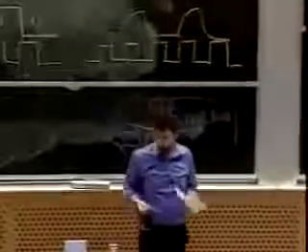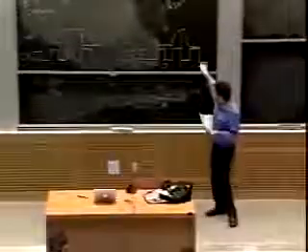If we're not careful, we're going to get something that's wrong. In this case, I transmitted 1010, but now I'm decoding something that's shifted from that somewhat. I'm decoding 0101. So I've become offset because the two clock signals aren't actually identical. Even though they're at the same frequency, they're not lined up with each other in time. So we say that those signals are out of phase, because one signal is essentially a time-shifted version of the other signal.